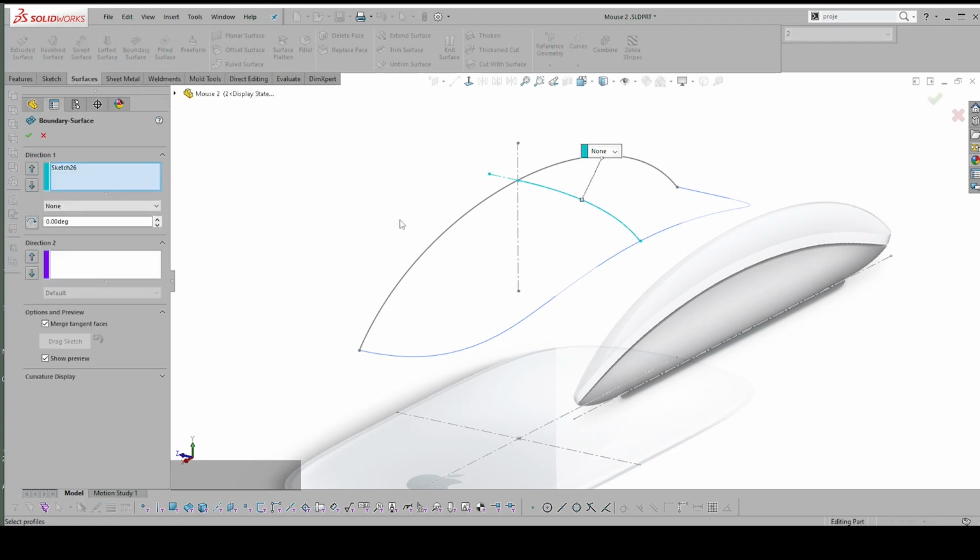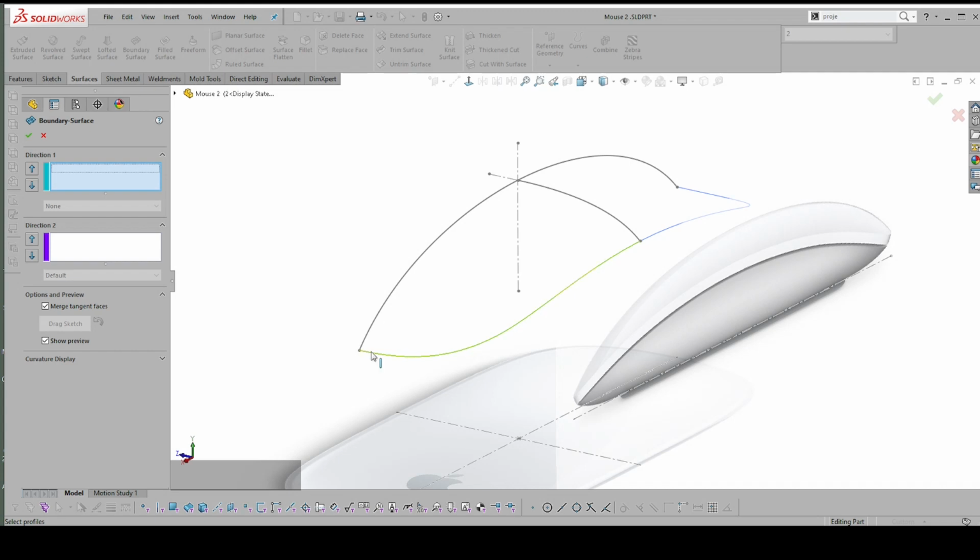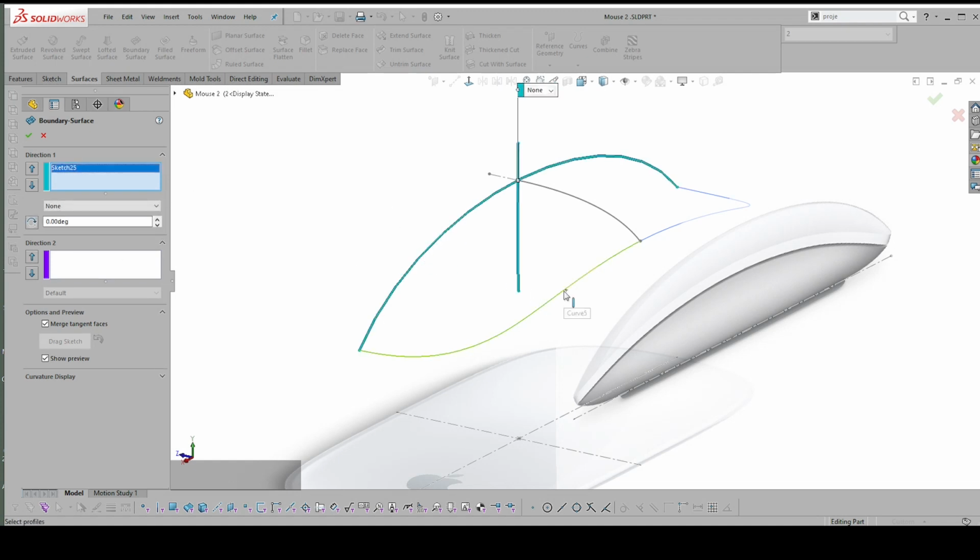Boundary surface isn't probably ideal. I think someone who knows about modeling would say, well, you're going to create sort of a corner here. There is a better way. I could actually split this curve and make 2 of them, but for now I want to simply illustrate the process. So I select those 2